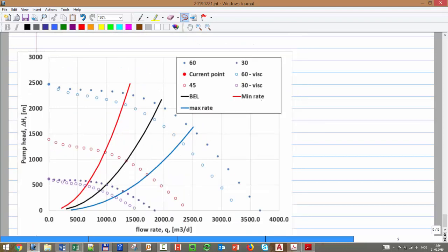You find from your equilibrium delta P and Q of liquid, and then you simply calculate delta H by taking delta P divided by density. And you plot your point, and your point falls inside the map, and the map is given by, you see here, that's the curve for water, and that's the curve when you have viscosity.